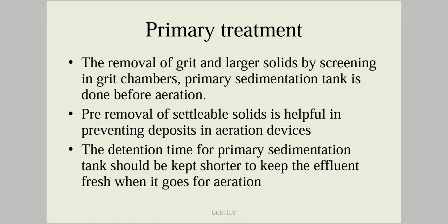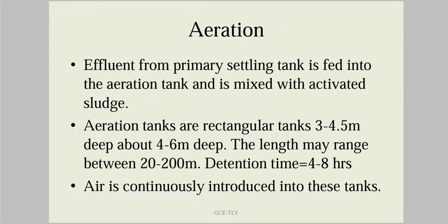So in order to remove that, in order to prevent the deposits from depositing there, we are doing this pre-treatment process. The detention time for the primary sedimentation tank should be kept shorter, so that the effluent will be fresh. Fresh effluent will be treated better in biological treatment. So the detention time of the primary sedimentation tank is kept shorter, and then it is taken for aeration.